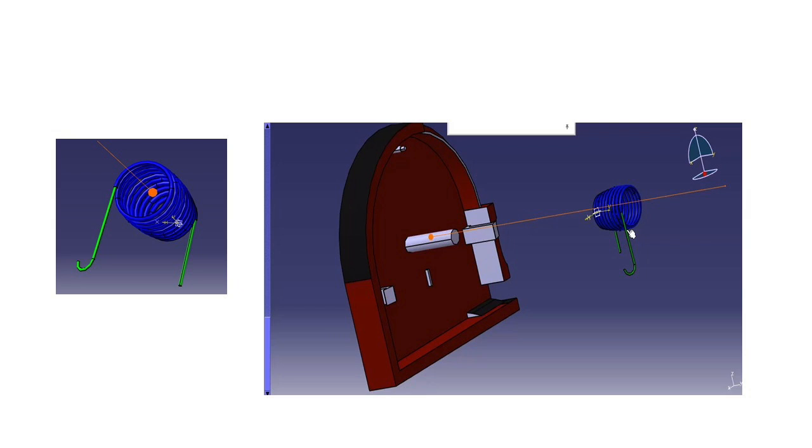There is a guider for the spring and a stopper in the bottom case. When the spring is assembled to the bottom case, the stopper arrests the spring rotation in the clockwise direction from the bottom end when the tape is pulled. To retain the tape in its original position, the tape rotates in the anti-clockwise direction and later the torsion force acts on it. This type of mechanism is generally used in old clocks, which are of key power type.